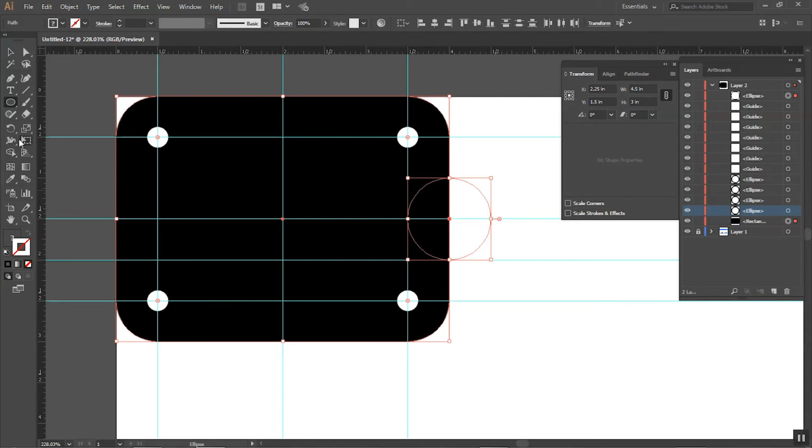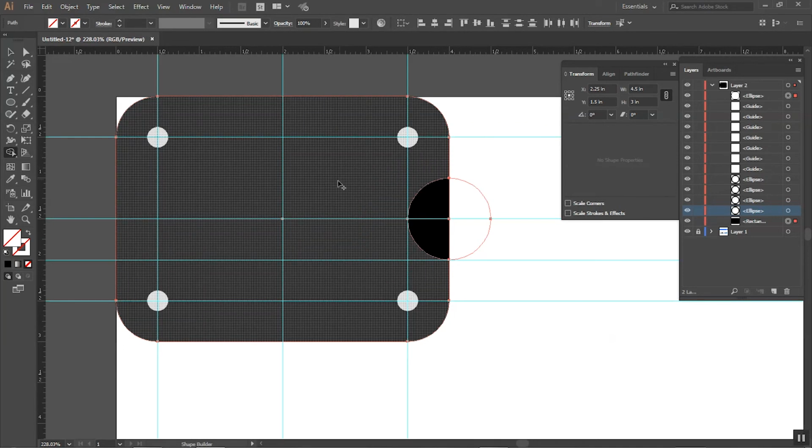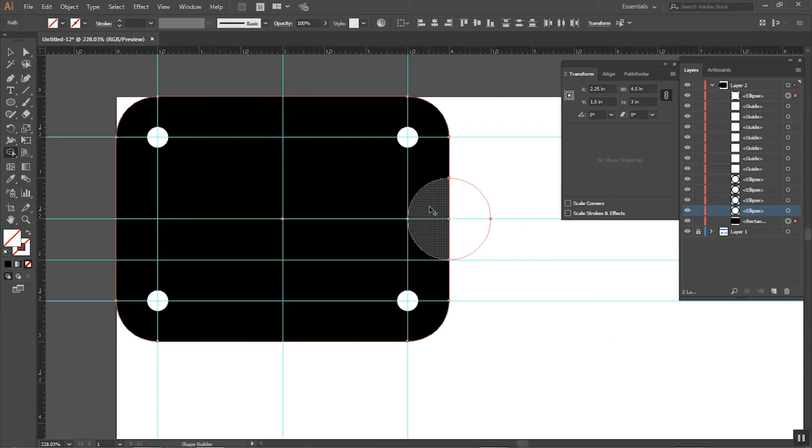So then I go to Shape Builder. I'd suggest you get used to using the Shape Builder. It's actually very powerful for a lot of these things. So you notice it says plus there. So it's just finding all of the profiles, much like Fusion finds continuous 3D or continuous closed shapes.